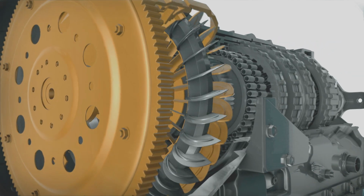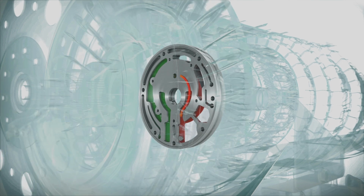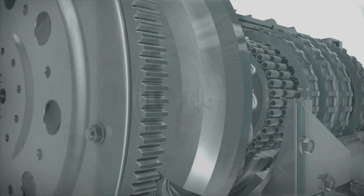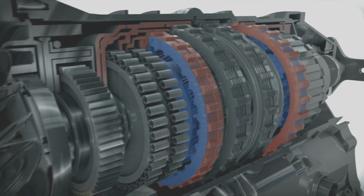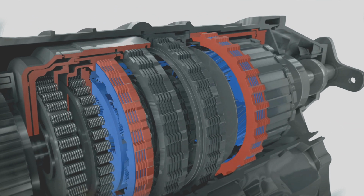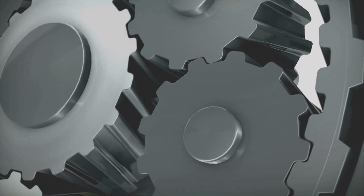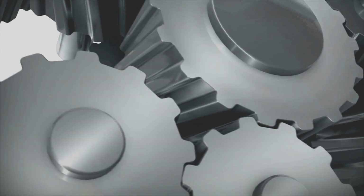At idle in park, the pump components spin, providing the pressurized fluid needed to operate the transmission. When the vehicle is placed in drive, clutches connect the gear set for first gear to the wheels, and when you release the brake, the car begins to move. The gears are engineered to withstand the extreme pressures and wear of continuous high-speed operation.